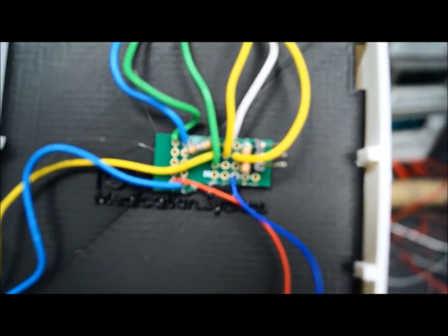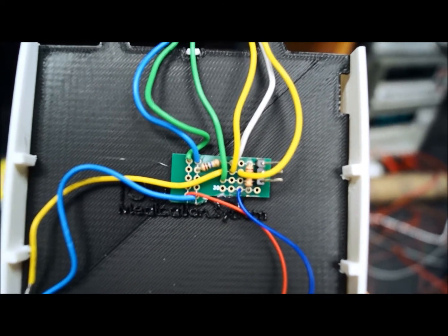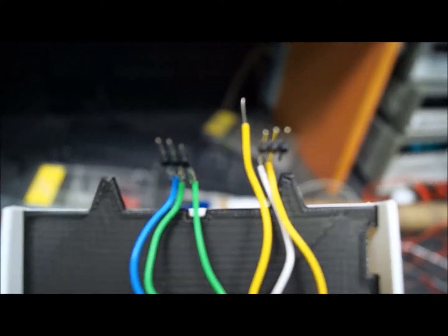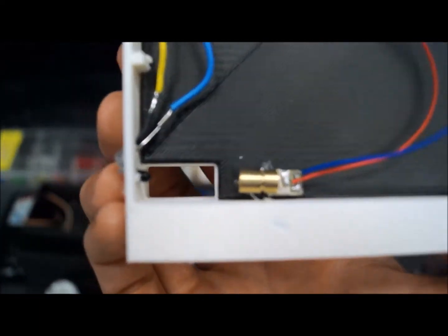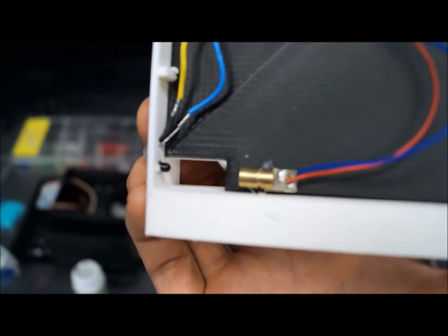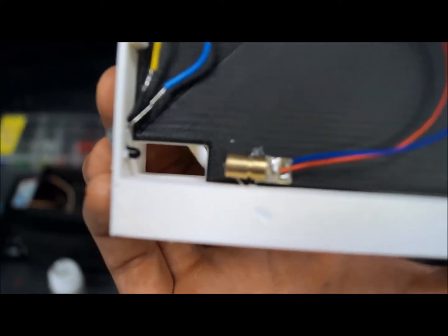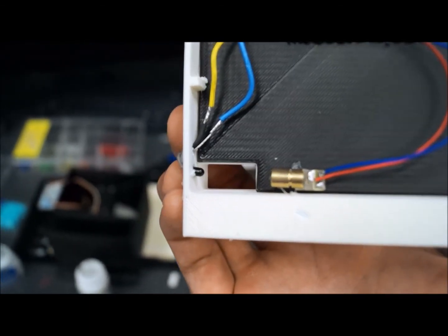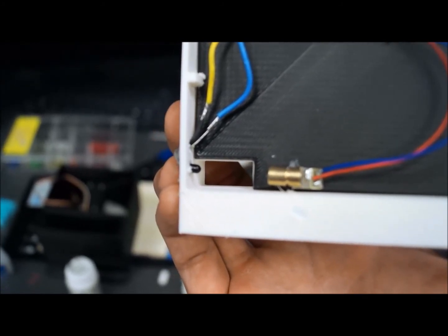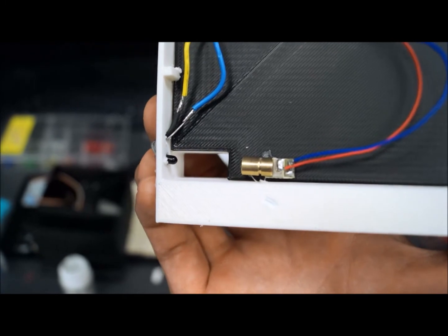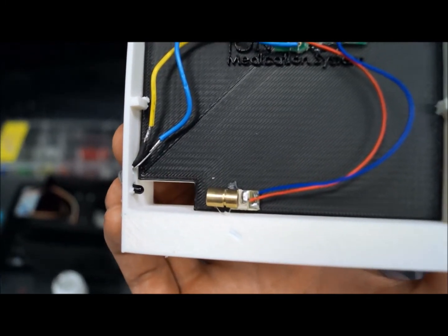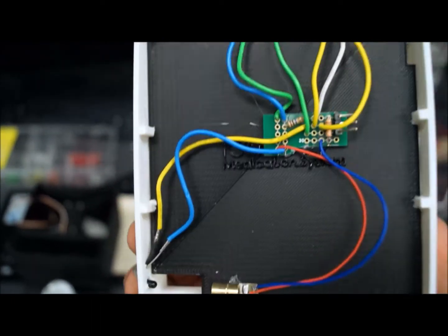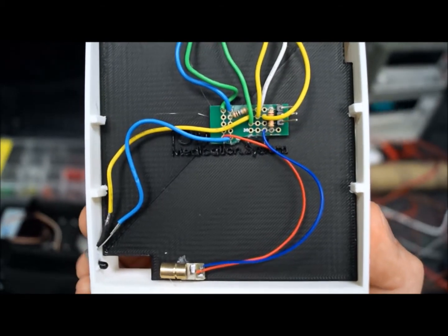We have a small circuit board here, which serves mainly to provide an interface for the main system. We have wires coming out for power and for signal. The pill detection comes from a pair of devices, the laser diode here and the phototransistor. When a pill goes through, it will break the beam, and that will send a signal to the Arduino to say that 1 pill fell through. If 2 fall through, usually it will be able to detect that as well. And that's it for this component.